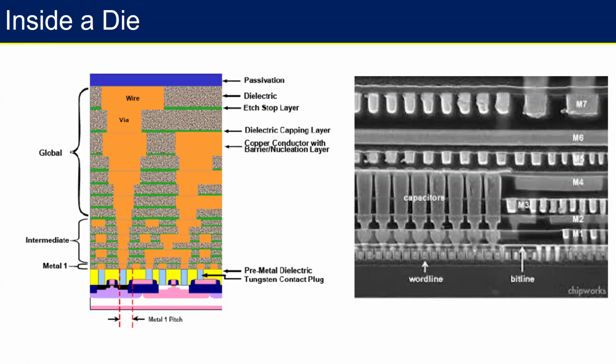So flyovers are a way for you to reach rather than going through the transistor layer. Let's say a transistor here wants to connect to a transistor which is very far. So why do I go through the first layer? I can go all the way to the top and then come back to that transistor, right? So that is why these metal layers are typically made. And the whole purpose of these metal layers is to connect these transistors to each other reliably, right?